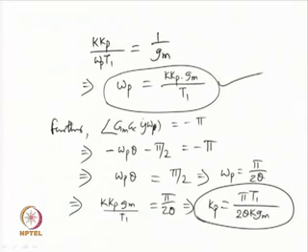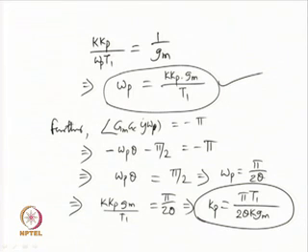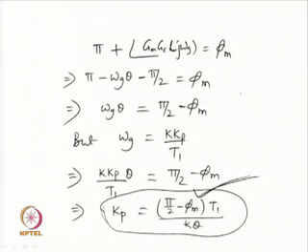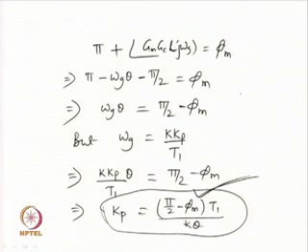So, this is the final expression we have got for the proportional gain of the PID controller: Kp is equal to pi T1 upon 2 theta K GM. So, choose some gain margin for the closed loop, and as you know T1 and theta and pi, you will be able to estimate the proportional gain of the PID controller, either using this formula or using this formula. Okay. Either using phase margin or using gain margin values, it is possible to estimate the proportional gain for the PID controller.